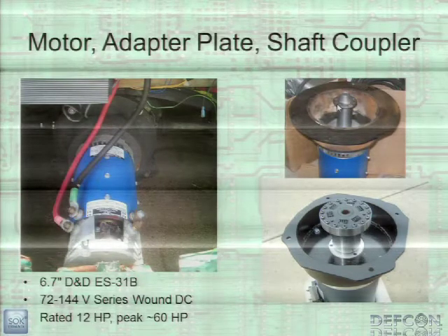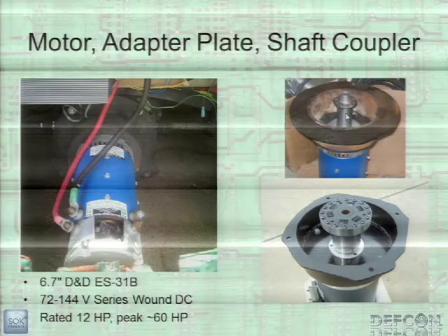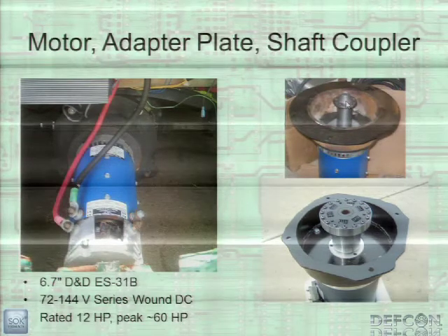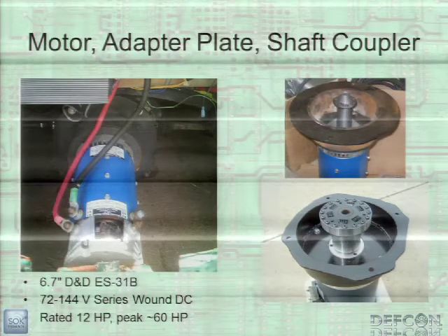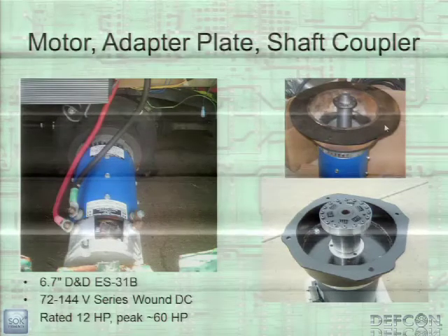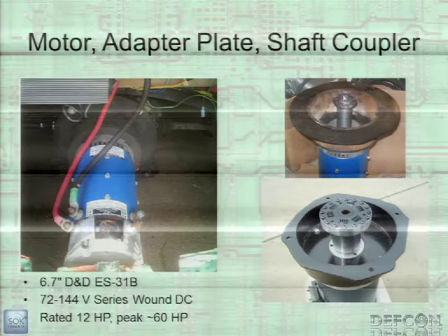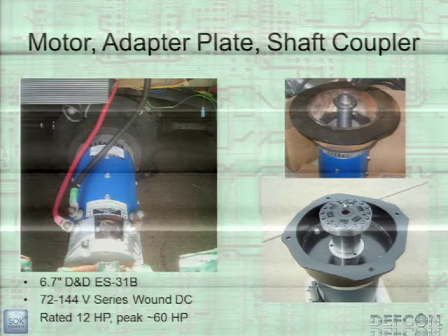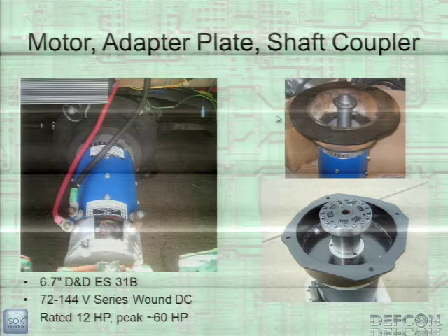This is what my original shaft coupler looked like. It's basically part of an old clutch disc that gets welded onto a coupler that goes onto the electric motor. After a couple thousand miles, the teeth on mine got worn off, so I had to replace it with one of these springy types. They're supposed to be a lot better and last longer.